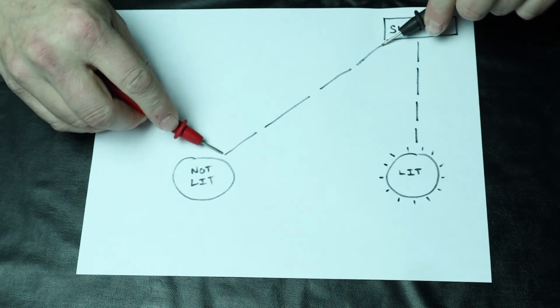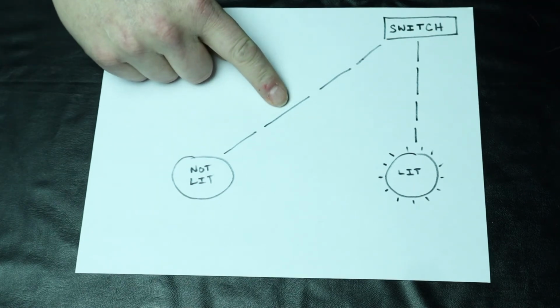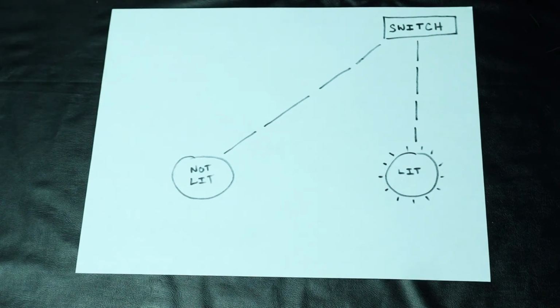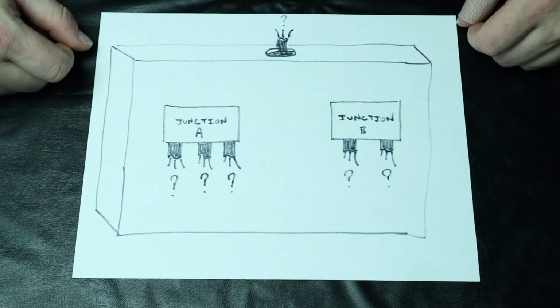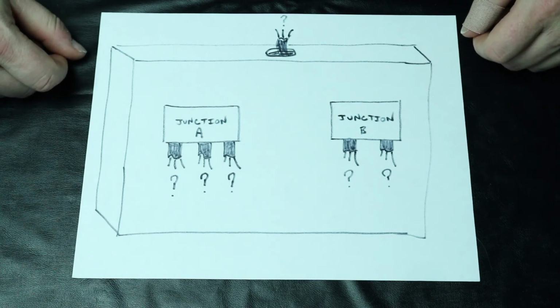Finding that there is in fact no continuity, and there should be, I then physically examine the wires and find that one of the wires has been chewed in two by some unsympathetic creature. Delicious. Another example might be if I'm trying to trace a wire from one exposed junction in a wall to another. Let's say there are 3 sets of wires in junction A and 2 sets of wires in junction B. If the wires are run inside the wall, I cannot physically see them in order to determine which of the 3 sets in junction A matches up with either of the 2 sets in junction B.